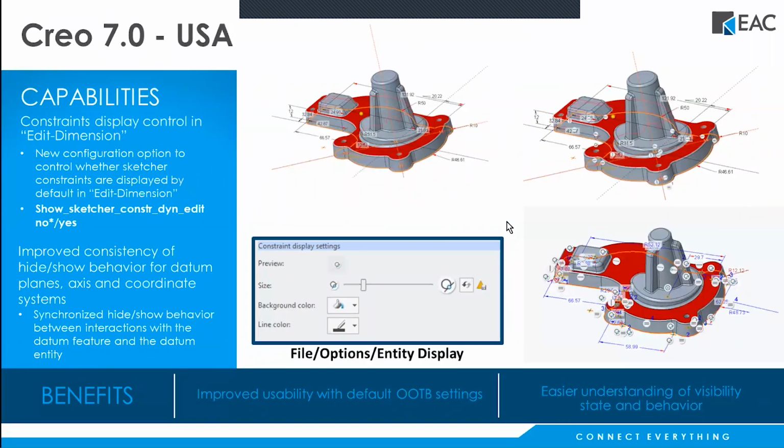And then kind of speaking of sketches, one of the things that we can do is that usually when we go and edit the sketch, obviously the dimensions for that sketch appear, but we can also now include the Sketcher constraints. So sometimes that can be useful to you when you're looking at this sketch and maybe it wasn't your part or somebody else's, and you can kind of see, oh, this is supposed to be a horizontal line, or this one is equal length to this line, or something along those lines. So we can see those little icons displayed when we say, edit sketch.